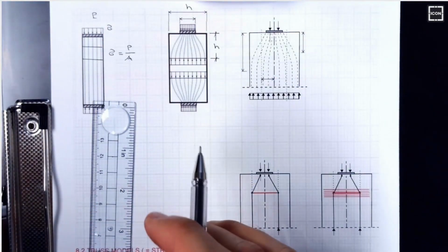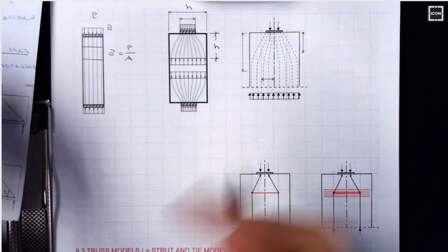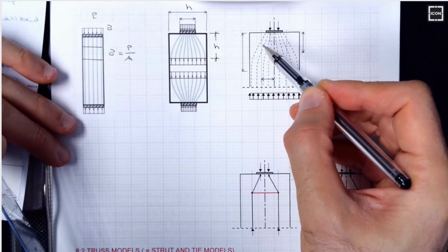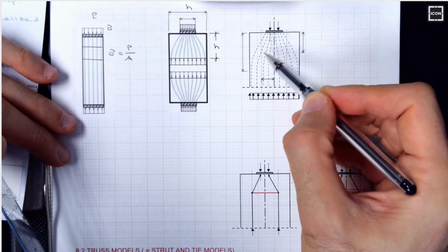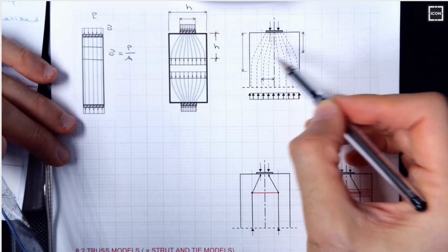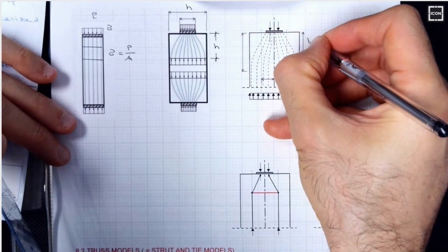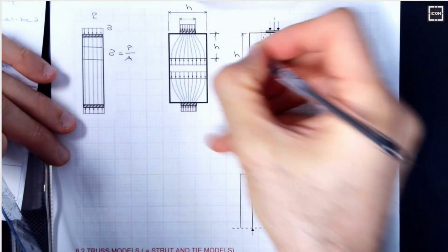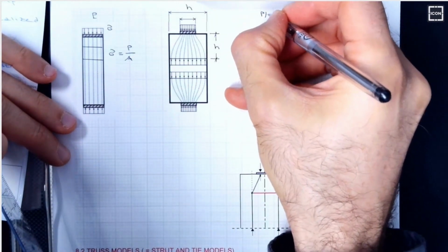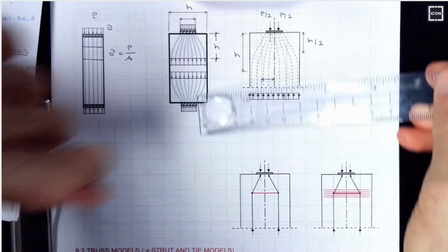So what is creating that split is the tension, because whenever stress changes direction, as you can see, stress is coming in this direction. It's like a stress flow. It wants to occupy the entire member. It does eventually, but it needs some distance, which is shown here. Call this h/2, and this is the entire disturbed region, which is h. So the force, you can divide into 2, p/2. This is p/2 in this situation, right?